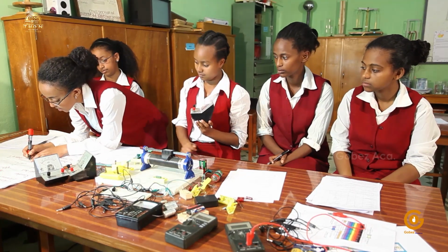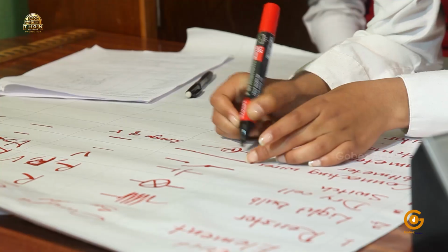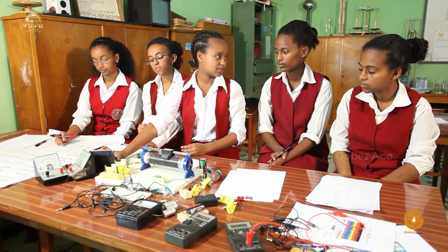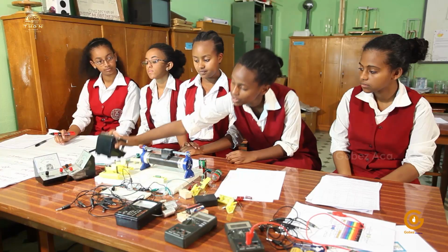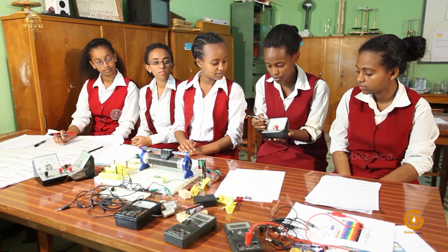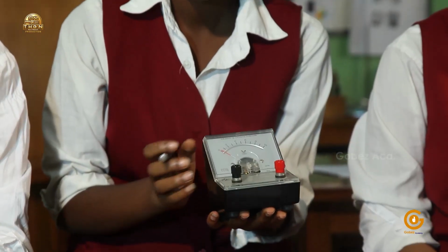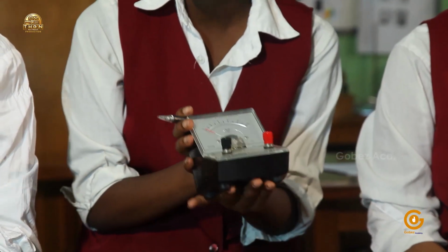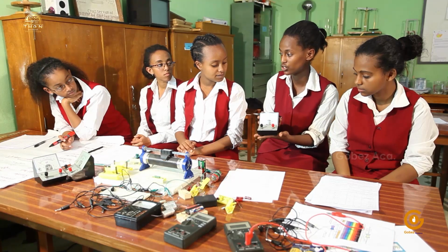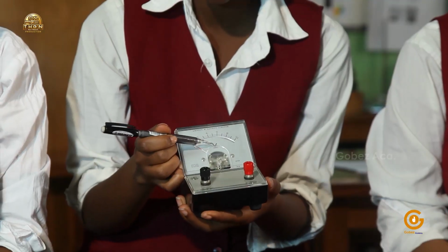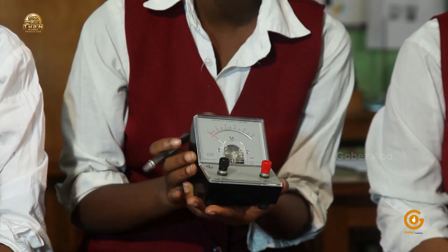It's a V inside a circle with 2 lines extended out of it. So what's the characterizing quantity for a voltmeter? Well, as you can see here, it shows that the voltmeter has from 0 to 10, which means it can only measure from 0 volts to 10 volts, which means the range of the volt. And the fact that there's a line underneath the V shows that it can only measure DC.